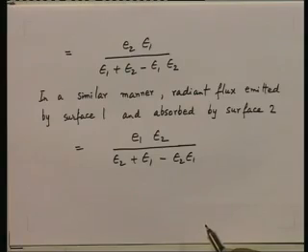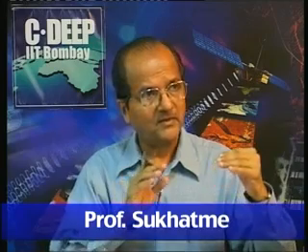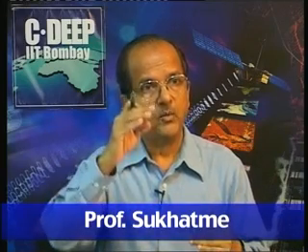Okay. So, I have now two expressions: the radiant flux emitted by surface 2 and absorbed by 1, and the radiant flux emitted by surface 1 and absorbed by surface 2. I take the difference of the two, and that is the radiant heat flux exchange between surface 1 and surface 2. So, we will get the radiant heat flux exchange between surface 1 and surface 2 given by, let us put that down now.